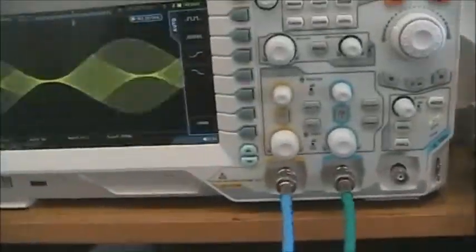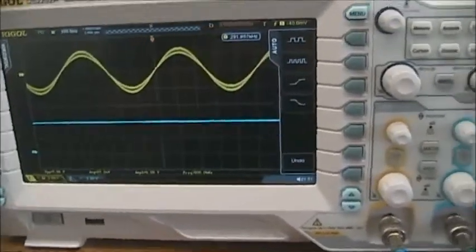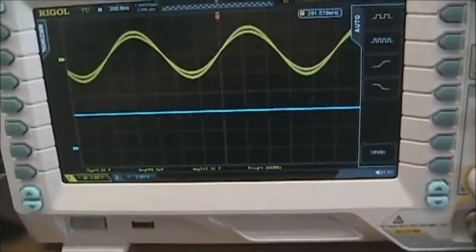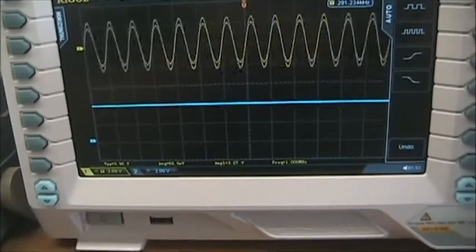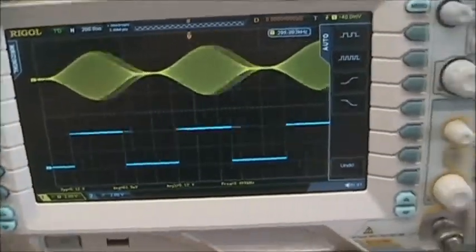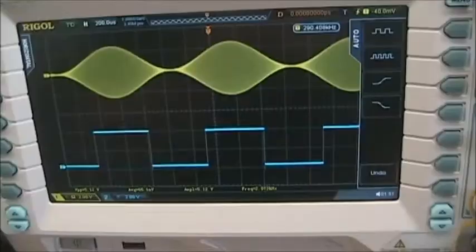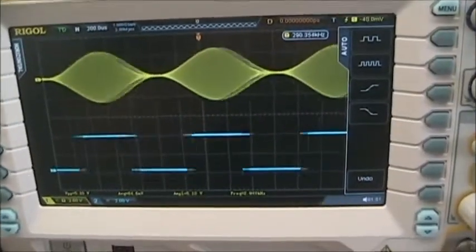So I've connected that up to the scope. Now let's run the auto scale here. And we see the typical display, again with the AM signal being a little jumpy. Now, the square wave, which is at 1 megahertz, from the sync signal, we will use that for our trigger.